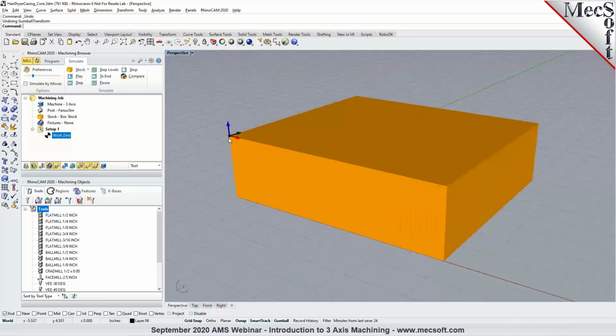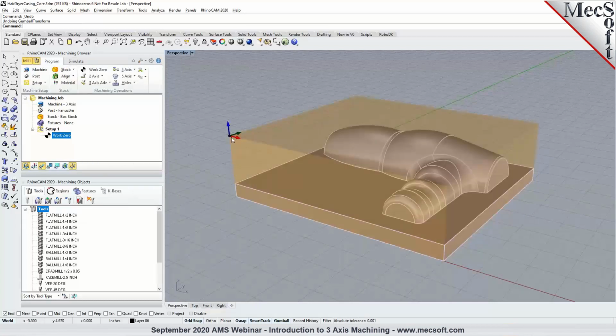So when you place the workpiece on your machine tool and establish your 000, your touch off point would be the top of your stock material and the southwest corner. You'll notice in this particular example, the XYZ origin for machining is set to the top of the stock material. Your world coordinate origin still remains for the part design at the bottom.